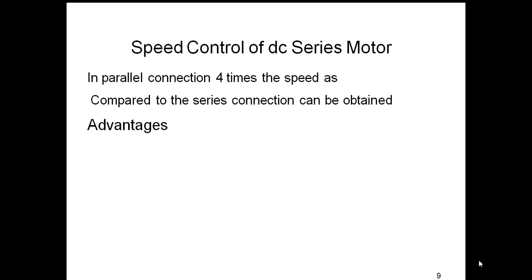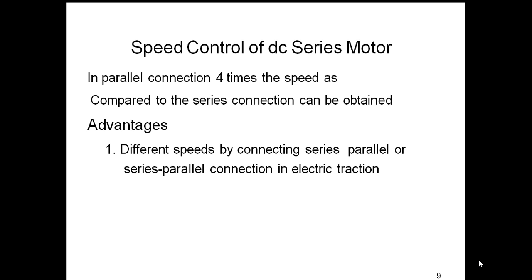The advantage of this method is different speeds can be obtained by connecting series, parallel or series parallel connection in electric traction system, and this method is used in crane tractors due to its high starting torque.